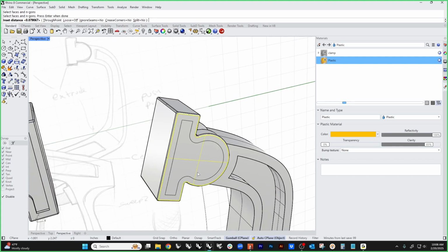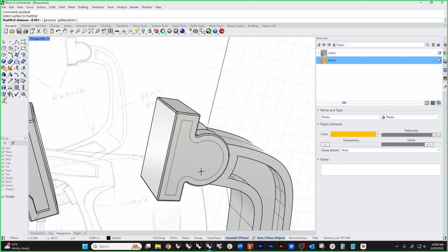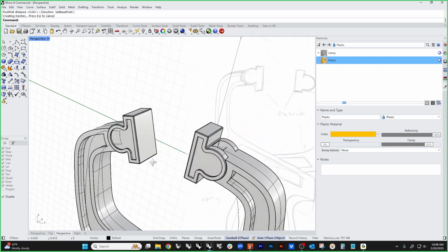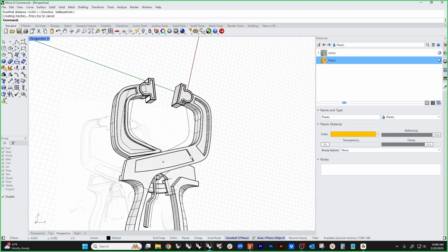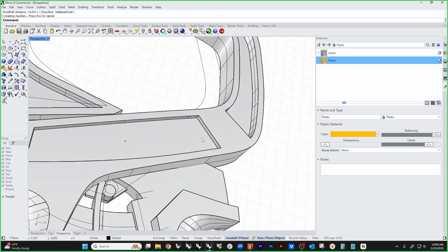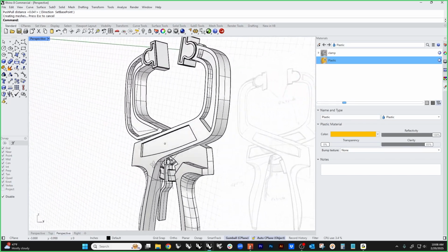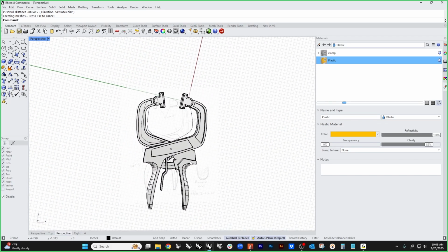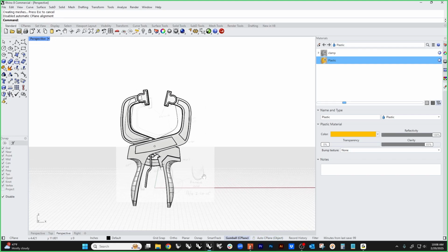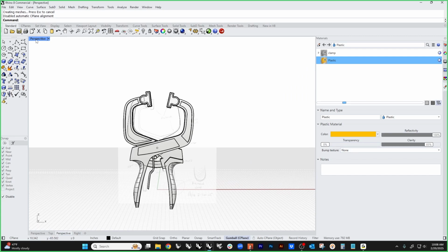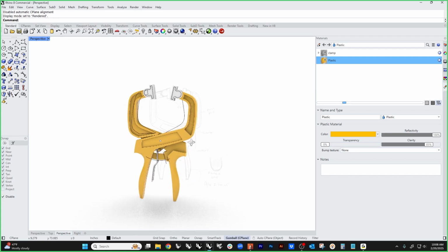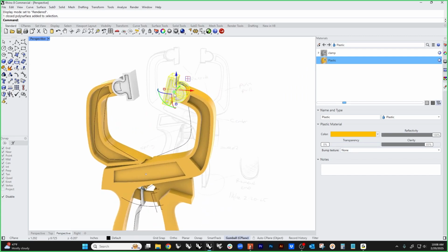So Inset, push-pull, like that. And then we can start playing around with, like, do we want to fillet stuff and all that kind of stuff? Or we can cheat and we can apply edge softening in the render mesh. All right, let's say these are a different color plastic.